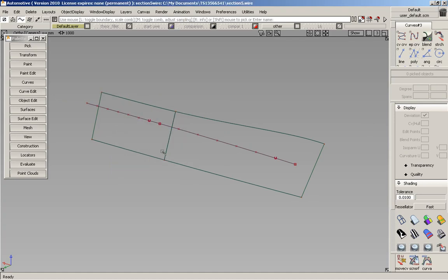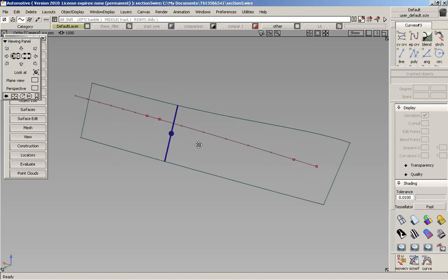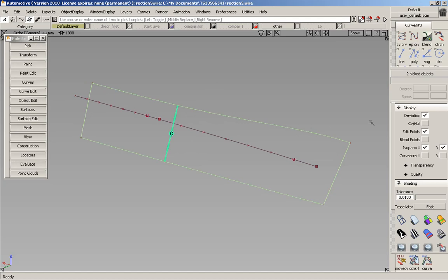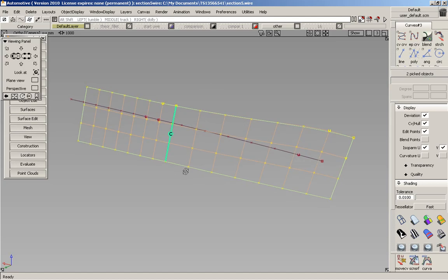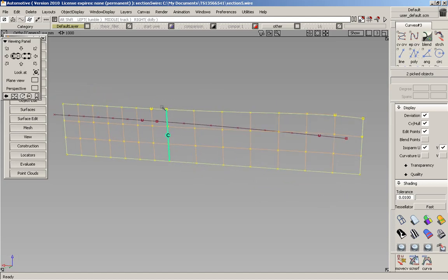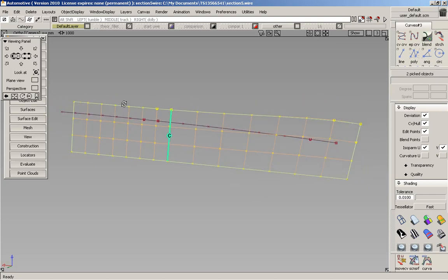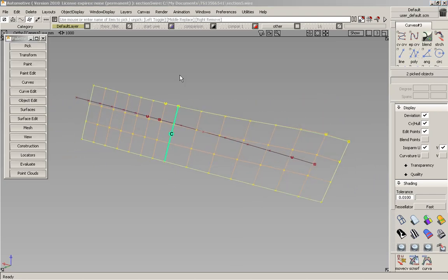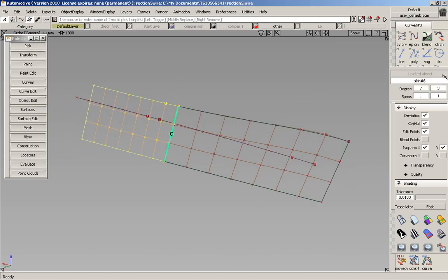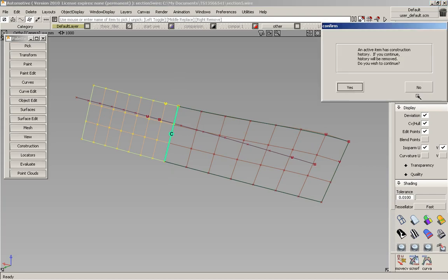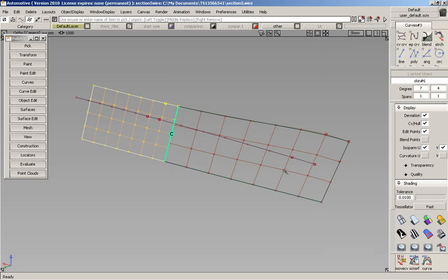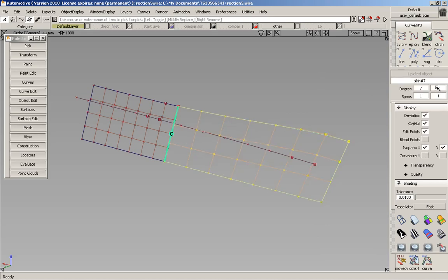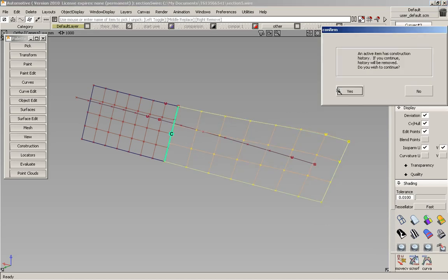Now we're just going to turn on our continuity indicator. We have curvature in between the skins, and we'll just turn on our CV hull structure there. So now we have a CV hull structure that's flowing with our theoretical. Now we're going to add another degree in here to give some more control when we do our direct modeling, just to make sure we achieve the proper continuity levels.